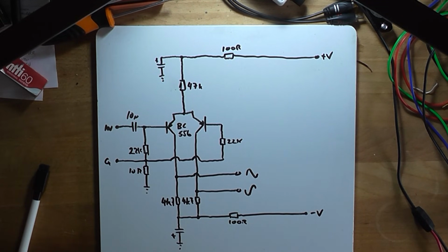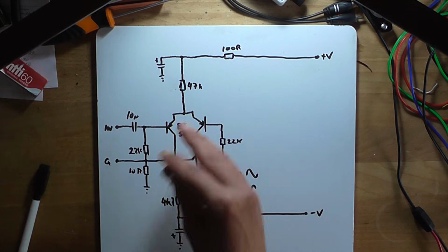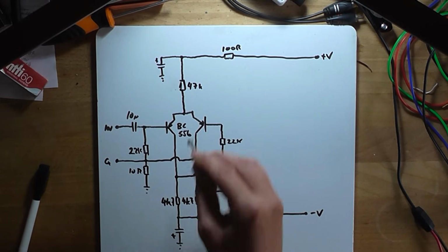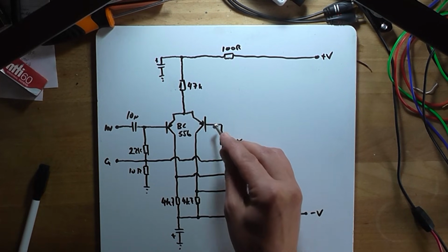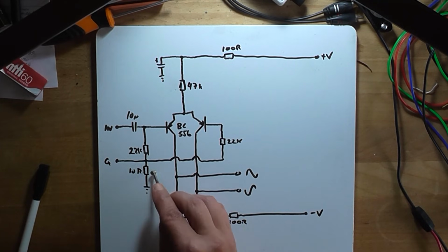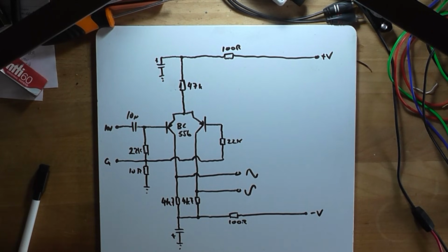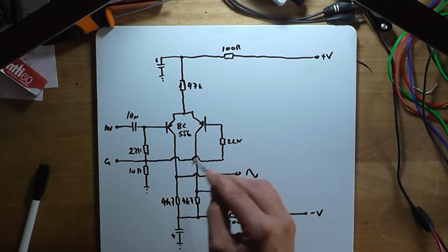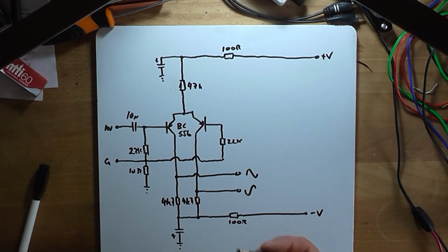So let's go to the breadboard and have a look at that particular circuit here. This obviously is not going to be the final design because we wouldn't have this base 22k resistor going to ground, which is earth lifted by this 10 ohm resistor here. But it gives us a proof of concept of how this stage actually is supposed to work.